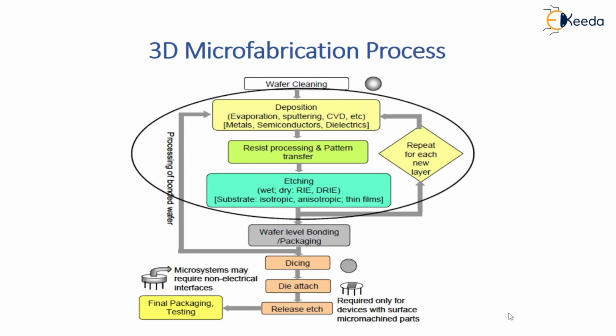Okay, that is for pattern transfer. While in the lift-off condition, we coat the resist, do UV exposure and development, then metallic deposition, and removal of resist and unwanted metal. So in the lift-off process, the photoresist pattern is generated initially on the substrate, and instead of etching, the unwanted material is removed. Okay, so that is considered in resist processing and pattern.